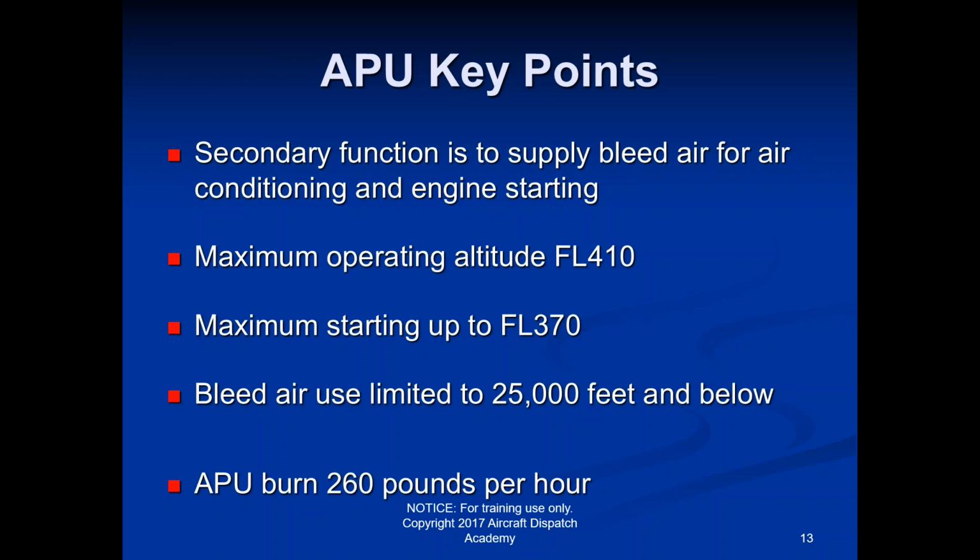and if we find out about it before it gets there, then we will have the airplane leave one of the engines on while it's on the ground. It's kind of a tough process, because in order to fuel an aircraft, you're supposed to have the engines off on the side that you're fueling. So you have to go through a lot of different procedures with fueling and with passenger loading and unloading. Sometimes you have to switch the engine that's on from the left side to the right side, and then vice versa. You've got to switch it back, shut down, redirect the air, turn on the other one, shut down that one. We call it a hot turn in the airport ops world.